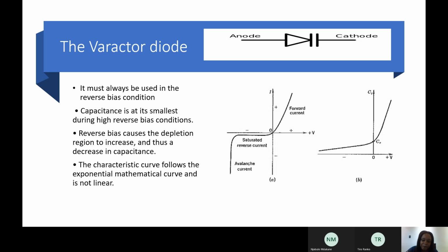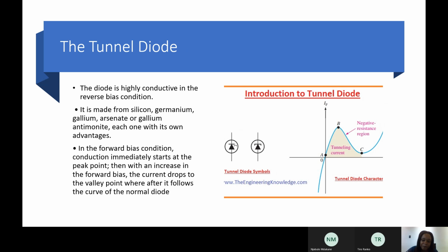This one is what it looks like with the voltage and current characteristic curve, but this is the voltage and capacitance characteristic curve. You can see in reverse bias mode the capacitance is low, and in forward bias mode we have a huge amount of capacitance going through the two types of material, the PN. Okay, so that's what we know about the varicap. It's not really much.